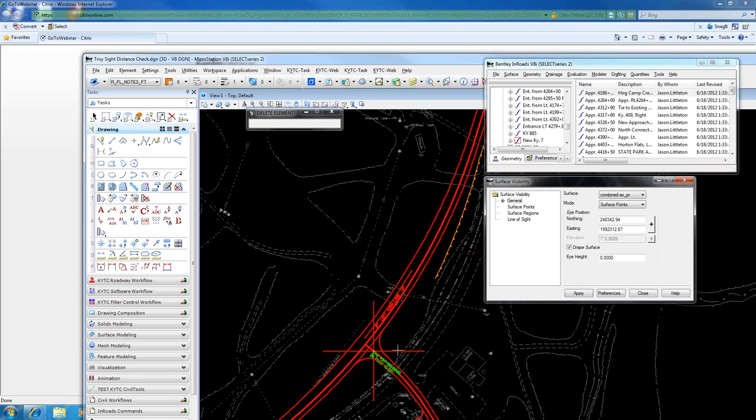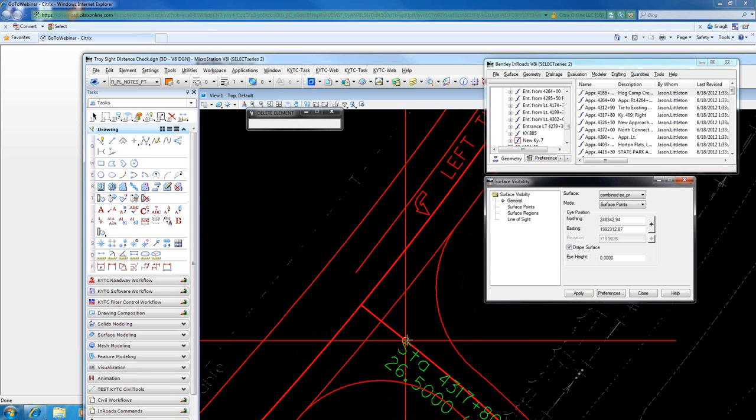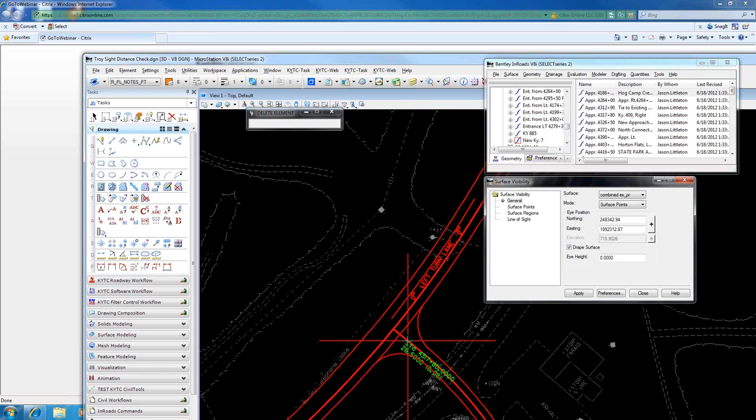Chapter 9 of the Green Book has explanation of intersection sight distance. I'm using 14.5 feet off the edge of traveled way. I think it recommends 14.5 to 18, with 18 desirable or something like that. But you can look up all the specifics for your case, because there's different cases for if you're turning right or left, or whether it's signalized or unsignalized or stop controlled. So consult your Green Book for the engineering. I'm just going to attempt to show you how this tool actually works.